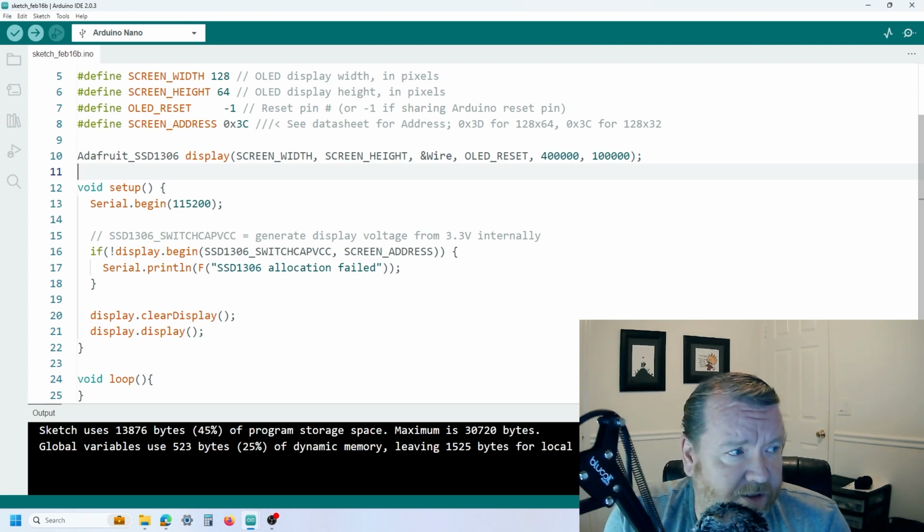So already this is doing something which I don't like, which is changing the clock speed for different devices. I believe it's okay as long as all the devices support the maximum speed. But if you set a clock speed faster than one or two of the chips support, I think you might eventually get some reliability issues.